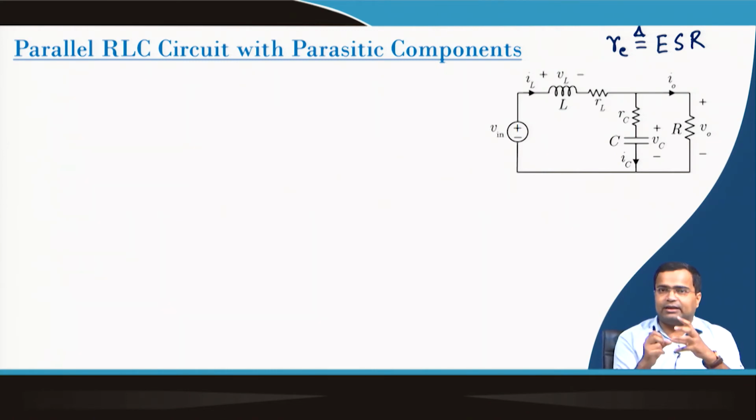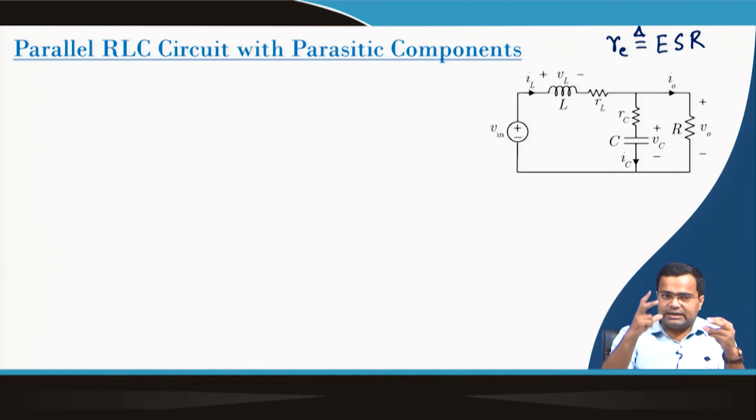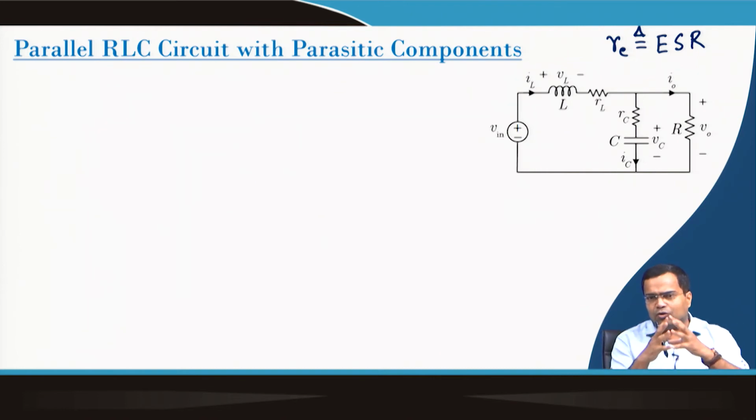If we start from the basic practical capacitor, as I told, with the leakage resistance, parasitic inductance like trace inductance, and trace resistance, and if you write the whole complex equation and separate out the real part, which is represented by RC, there will be a frequency dependent term, and that resistance also depends on the trace inductance and trace resistance.